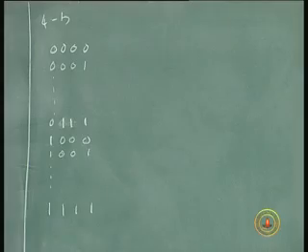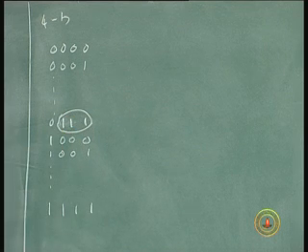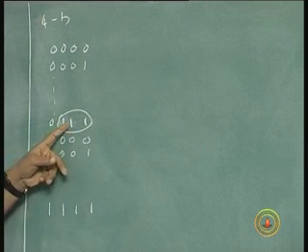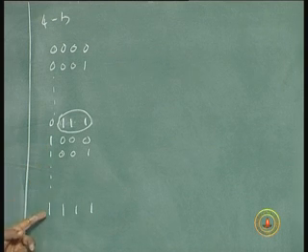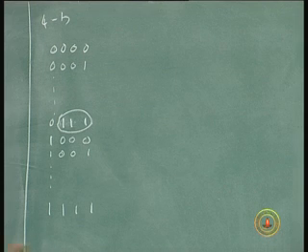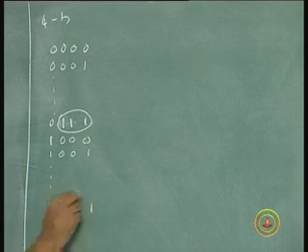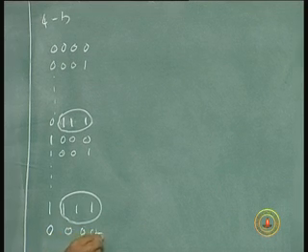Here these 3 becoming 1 1 1 will make the 4th flip flop toggle and remain the same, because after that not all of them can become 1 at the same time. Again all of them will become 1 at the same time here, when it will become 0, which is the same as this.